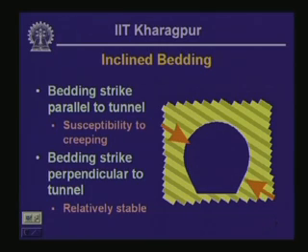What is going to happen as soon as the opening is made, because of the direction of the major principal stress, the rock mass within bedding planes, they are going to try to squeeze into the tunnel.